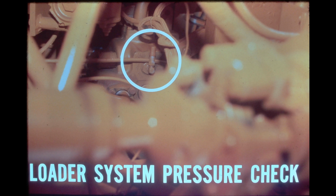If the pressure is low at both speeds, the pressure check should be made with the bucket cylinder bottomed out. If the pressure is still low, try adjusting the system relief valve. If the pressure is as specified at high idle but not at low, the relief valve is probably okay, but the loader pump is worn.